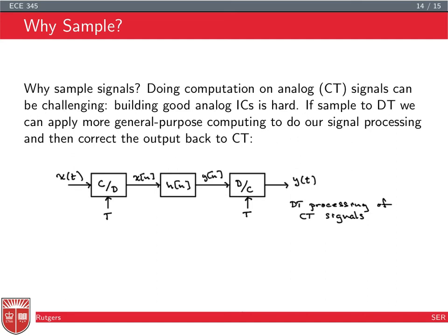The sampling theorem is a very important component, because most of the signals that we deal with in practice are band-limited signals, or we can make them band-limited by cutting off high frequencies that maybe are not audible, or, if we're talking about video, are not noticeable by the eye, or even depending on the quality of the video. If you want to compress more, maybe you cut more frequencies off. So you can make the signal low frequency or band-limited at the expense of some distortion or some quality, and then it'll be easy to process.